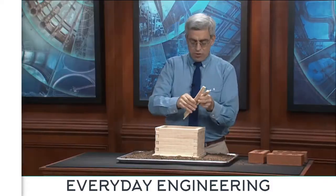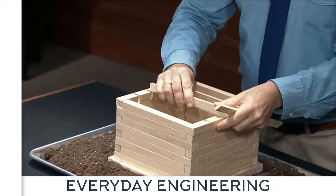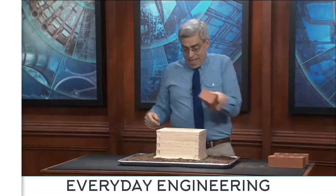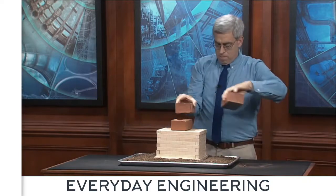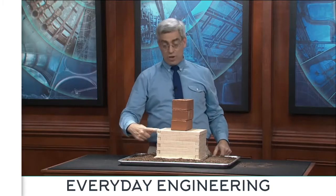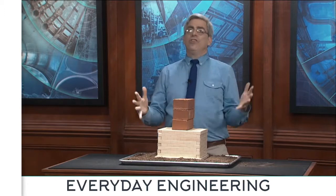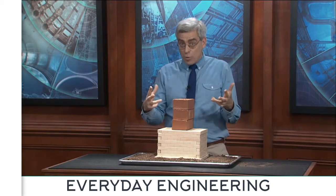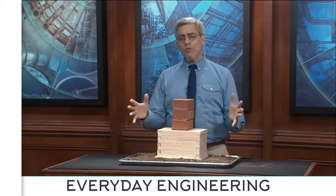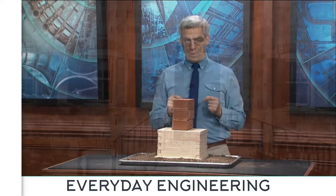Once again, I'm going to replace those joists set into notches in the two side walls. And now we can add that same gravity load. But at this point now, I can add substantial lateral load, not just in this direction, but in the perpendicular directions as well. And this structural system is now capable of resisting wind loads and gravity loads of significant magnitude. So clearly the rigid walls of a bearing wall structure provide inherent lateral stability.